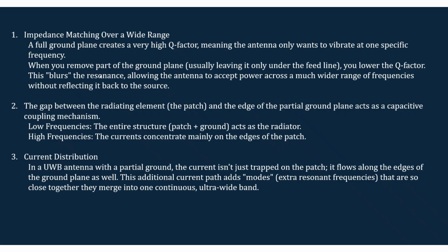When you remove part of the ground plane, it lowers the Q factor because the energy storage inside the dielectric will be less, and it gives rise to wider impedance matching. We have also observed that at low frequencies the entire structure, the patch and ground, acts as the radiator, but at high frequencies the current concentrates on the end of the patch, which gives rise to the wideband response.